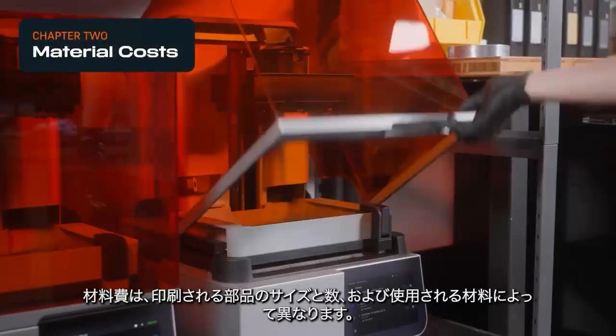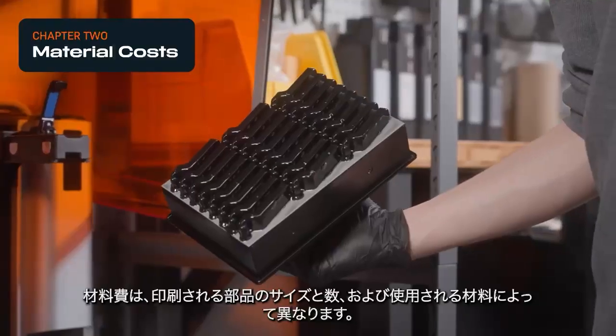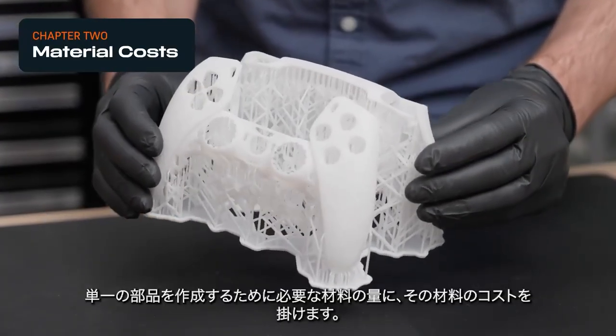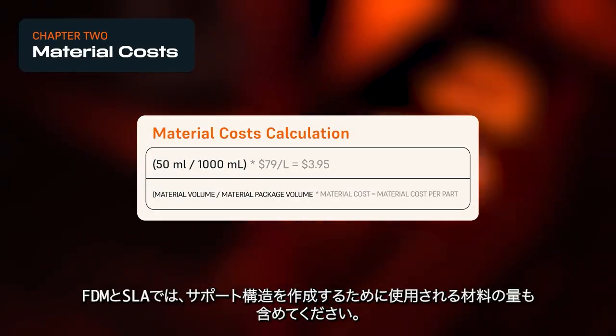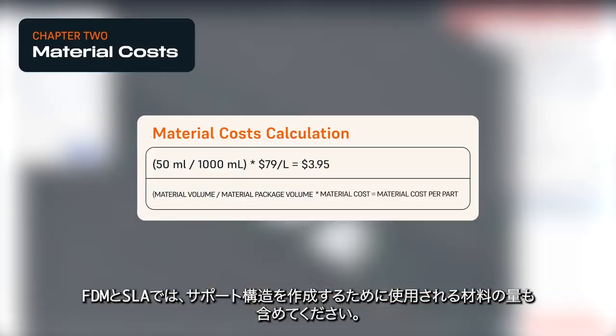Material costs will vary based on the size and number of parts being printed as well as the materials used. When calculating material cost per part, multiply the amount of material required to create a single part by the cost of that material. For FDM and SLA, include the volume of material used to create support structures as well.